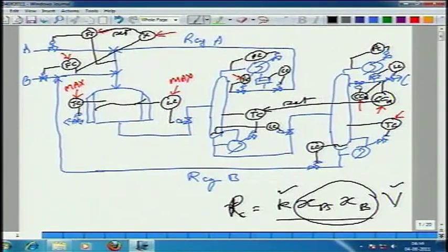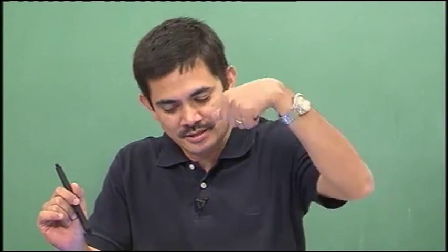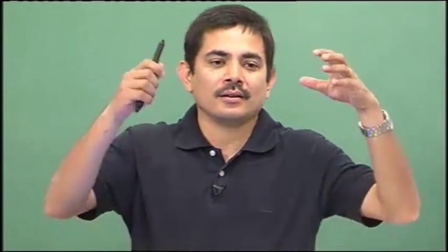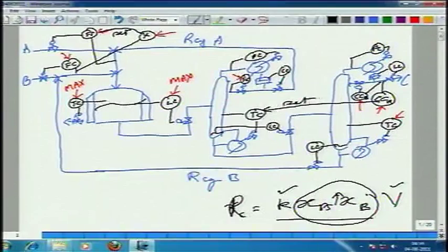So, shall we proceed further? So, how is the generation rate being increased? The generation rate is being increased by essentially jacking up XA and XB. Because XA and XB go up, RC goes up, generation rate of C goes up, however, XC does not go up, in fact it goes down slightly because of the dilution. Let us not, we are talking mole fraction.